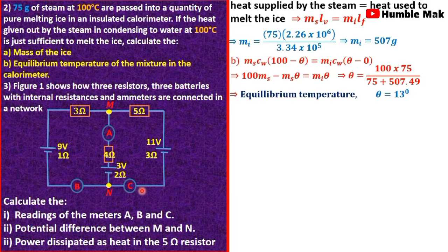Now friends, the question has not given us the direction of movement of current. It hasn't told us how the current is moving, but that is for us to improvise. We need to assign directions of current on our circuit. We have to do that such that all the sources with very high values should be delivering current, while those with small values should be receiving current.